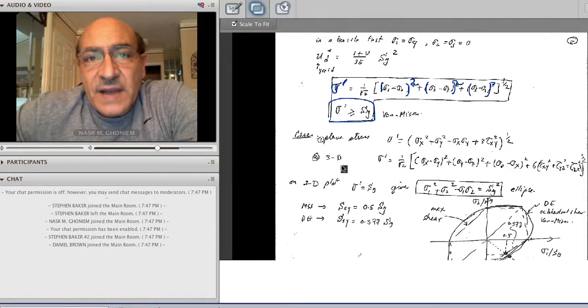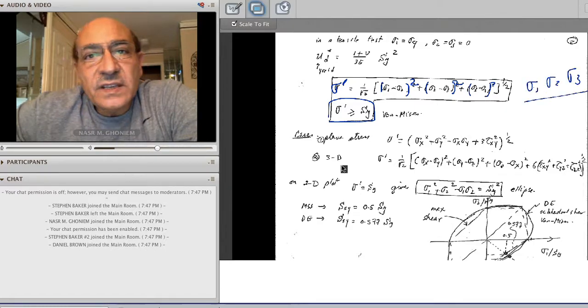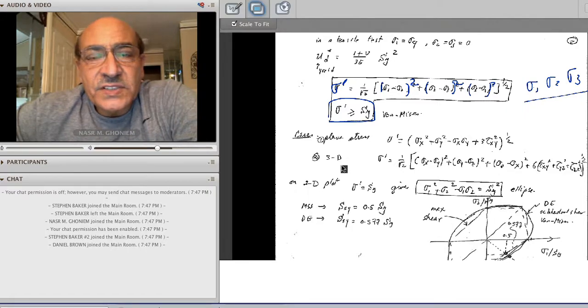So the step after this one would be to convert the stress state to its equivalent principal stresses. And for that we use the Mohr circle, for example. So to use sigma 1, sigma 2, and sigma 3, it could be laborious because number 1, I have to convert forces to stresses. Number 2, I have to convert stresses from their general form to the principal values.